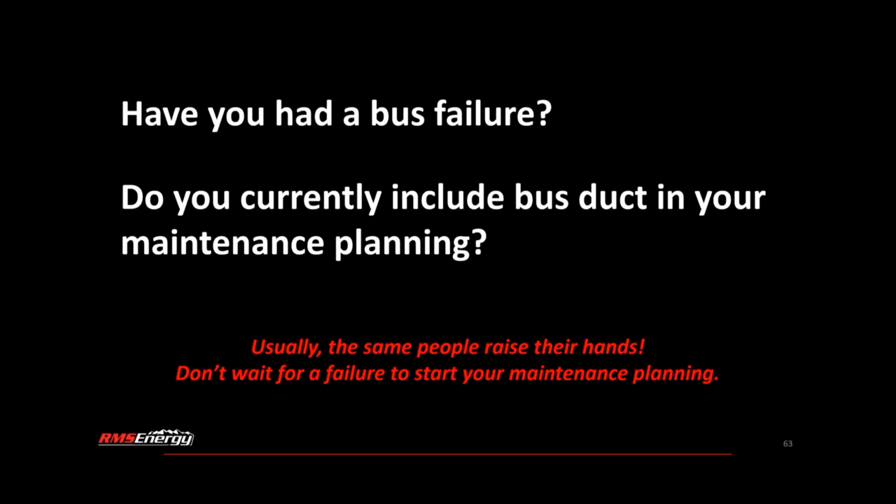If it's possible with the equipment you have, or you can access the equipment, I'd recommend the AC high pot, especially for non-segregated phase bus. But in lieu of that, there are different test values for AC versus DC to compensate for that. It's very common to DC high pot isophase, and there's really no major concerns with that. It's going to give you a good indication of what condition your bus is in either way.